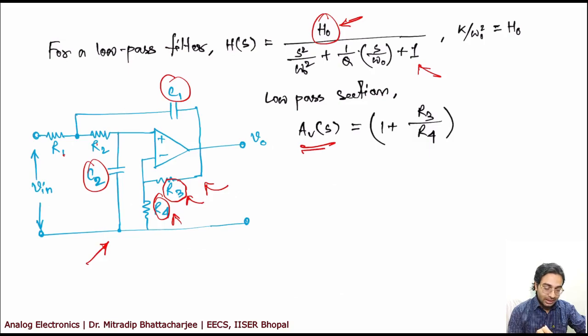Even if you put a gain function over here, for the low pass filter to function properly with stable values, you have a limitation on gain. You can't use any gain and put this filter into the circuit, or there will be trouble. So what I wanted to say is, it doesn't mean that you use an op-amp and just put in any value of gain and then use the filter.